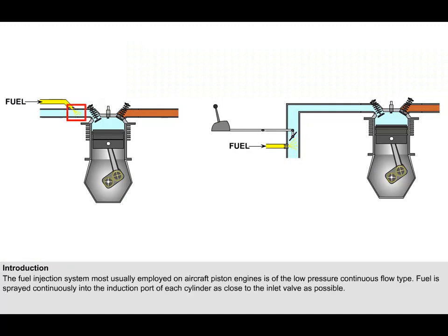However, the most commonly used system is the one highlighted here, where fuel is sprayed continuously into the induction port of each cylinder as close to the inlet valve as possible, and it is this type of system that we will study in this lesson. We will also look at the type of fuel injection systems in use on diesel engines.